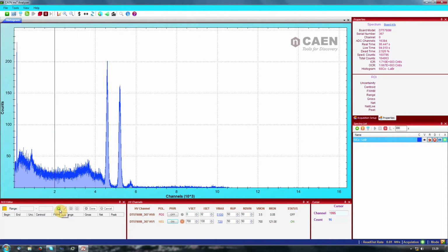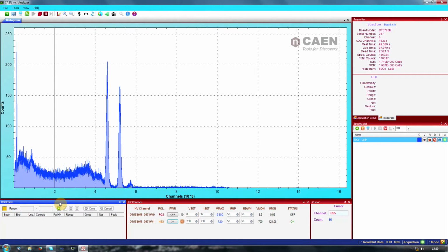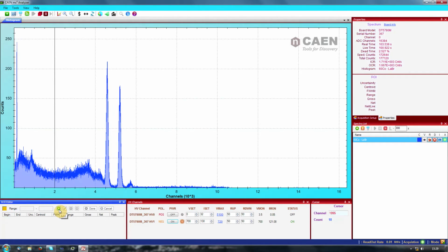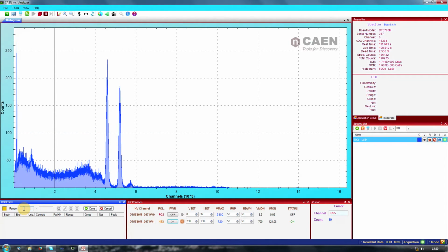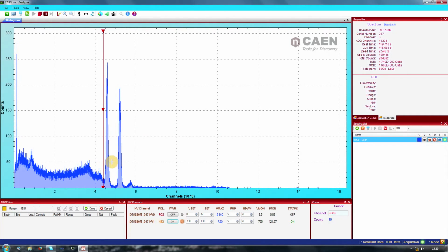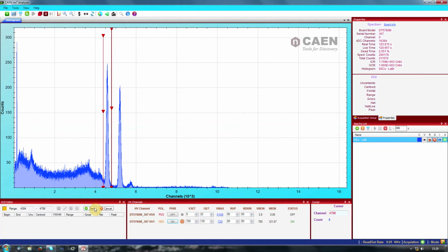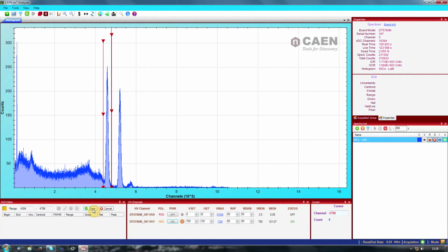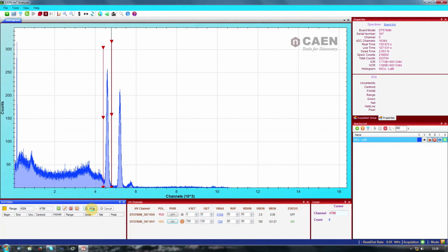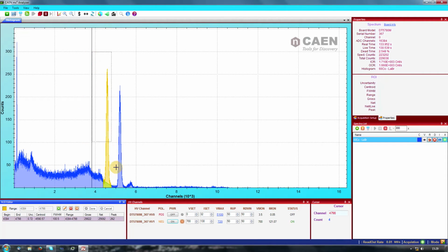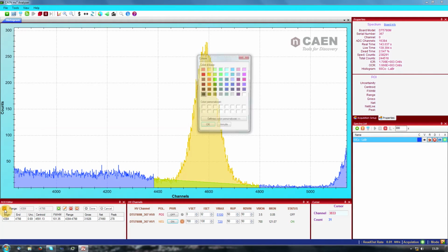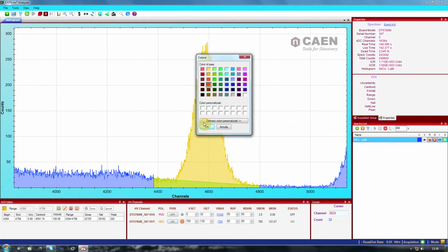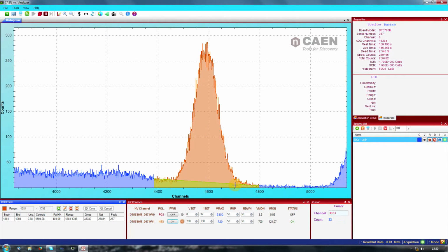The user can define some regions of interest, called ROI, through the option reported in the ROI editor window. To create a new ROI, we push the button Add, then we can write the starting and ending values expressed in ADC counts. Otherwise, we can set the ROI boundaries on the plot with a left click to start and another left click to stop. The user has to press button Done to confirm the ROI edited. When the ROI is created, its area in the histogram is highlighted by a different color, which can be changed in the pop-up window. The program shows in the histogram the estimated background.